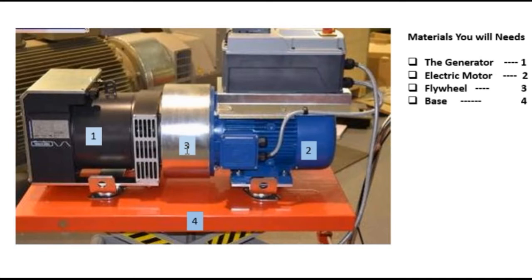I talked about the flywheel in very long detail, and I told you that the flywheel is the one that stores the kinetic energy that the system needs when you switch over from the external power supply to the internal power supply. The gap between the two of them is covered by the energy that is stored and needed.